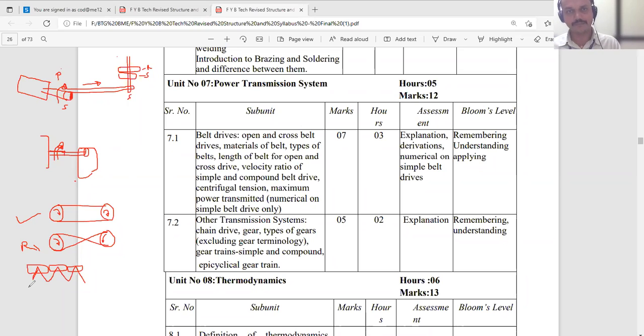is very small. Okay, why is it small? Why is the backside sprocket always small? Have you seen that for a regular bicycle? Do you have any idea? So it is because to increase the rotation. Whenever there is one rotation of the sprocket which is attached to that pedal, the backside sprocket takes 2 or 3 rotations, so it will increase the speed of the bicycle. It is called the gear ratio actually.